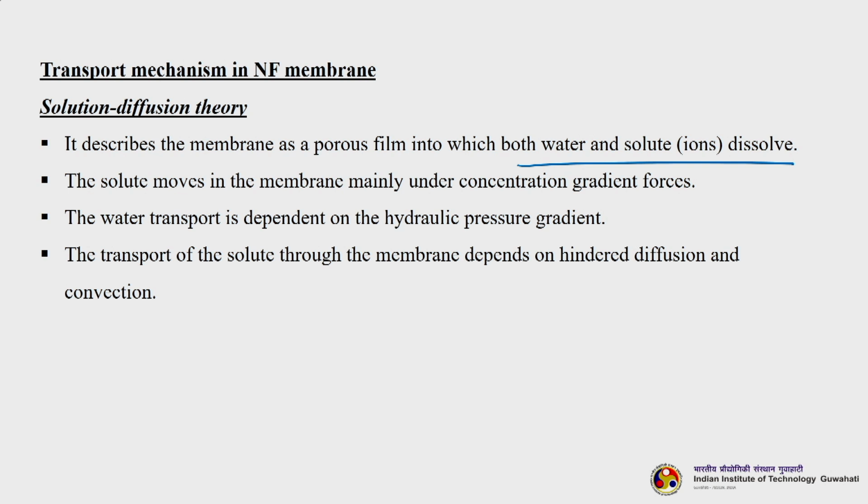So, the solute moves in the membrane mainly under concentration gradient forces. The water transport is dependent on the hydraulic pressure gradient. That means the more you supply the delta P, the more will be the water flow. The transport of the solute through the membrane depends on hindered diffusion as well as convection.